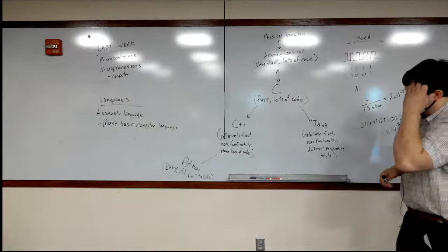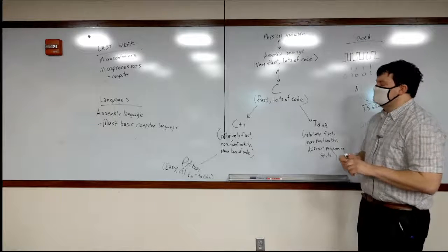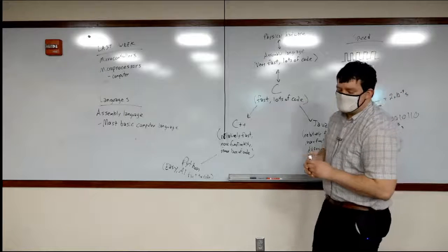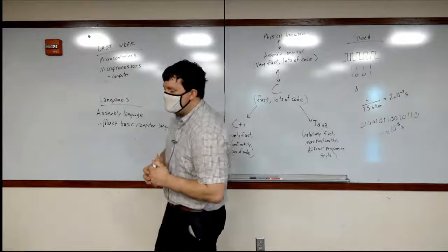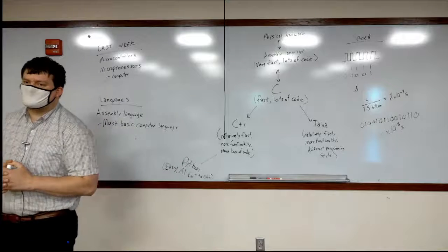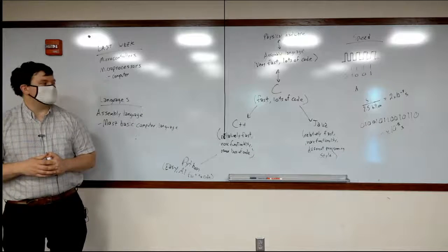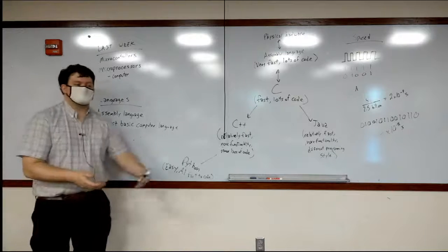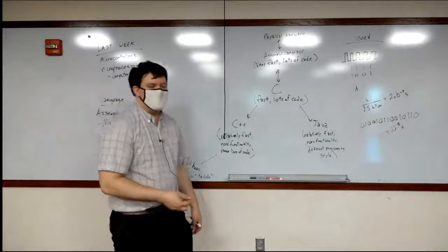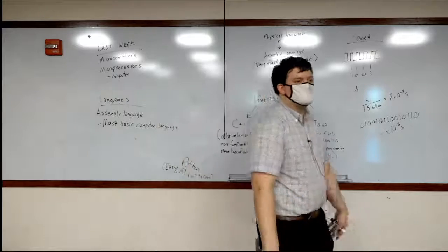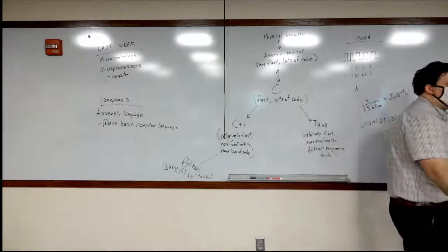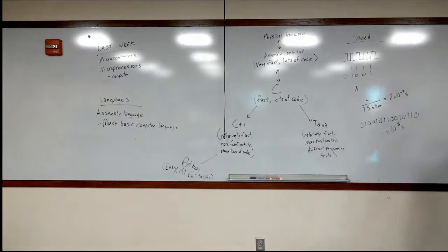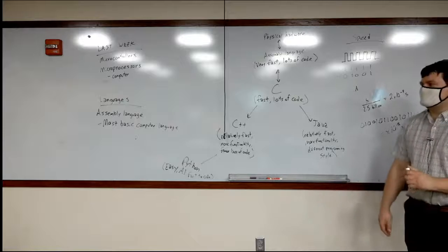Now that said, when you get into using microchips and microprocessors and microcontrollers, you may need 100th of a second level control. You may have something where you have to raise a flag if the sensor reaches a value that is too high. It has to be able to react within 100th of a second, because maybe 50 milliseconds later, you could have an explosion if it doesn't process that and immediately react to it.